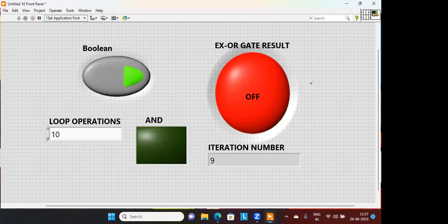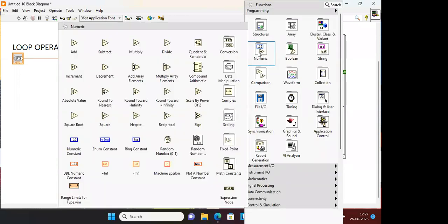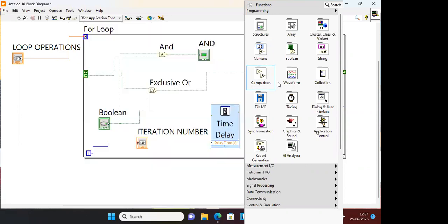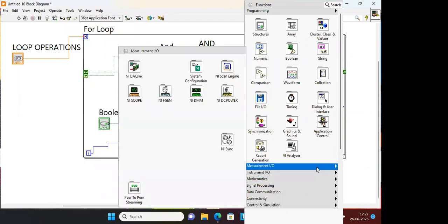So in LabVIEW, basically in signal processing, there are pulse width modulations. In that, you can have your pulse design. You can design your duty cycle, you can design your pulse, and then you can give a trigger on either the rising or falling edge. That's possible in LabVIEW, but ma'am, that's more related to the hardware. Whichever PLC you are using, those drivers have to be downloaded in LabVIEW, and then we can have a digital triggering on a rising or a falling edge.